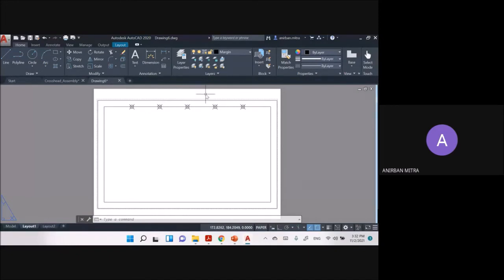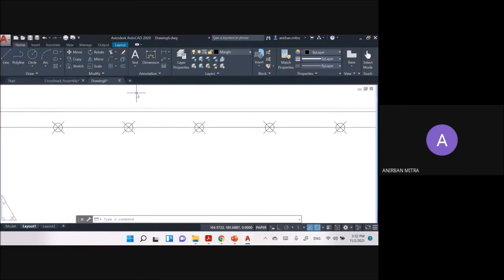Now let's zoom in just a little bit on that part. Now I can select this point and drop a perpendicular to the outer edge. I can also do this. I can switch on the ortho mode and drop this perpendicular. So select line using O snap, get hold of this point, and from here drop a perpendicular to the outer edge. So that is how I have created this line.